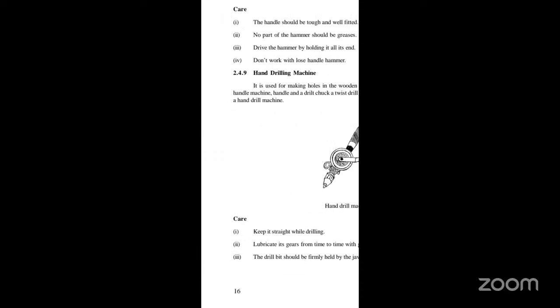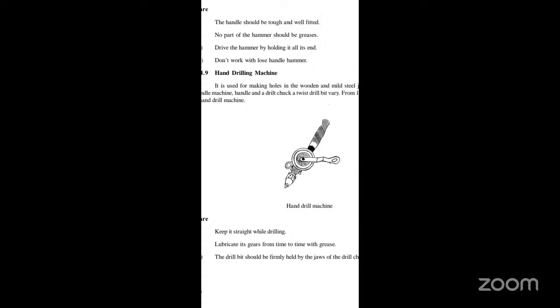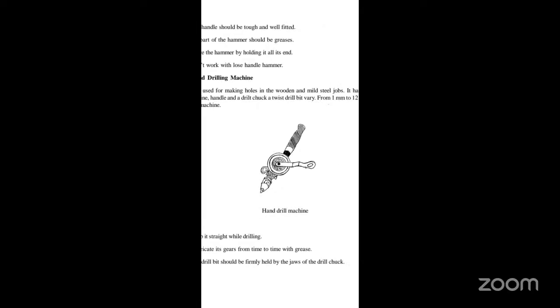Now, care. Keep it straight while drilling. Lubricate its gears from time to time with grease. The drill bit should be firmly held by the jaws of the drill chuck. So keep it straight while drilling.